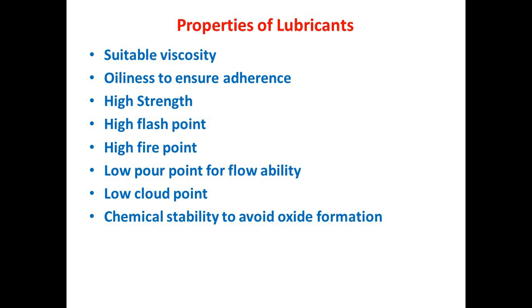Definitely, any lubricating film which is placed between the two components having relative motion between them, if this particular lubricating film doesn't acquire a high strength, then because of the forces applied on each other by the components, they may create an impression, or you can say scuffing, on the different components. So high strength is quite a major property for the lubricants.